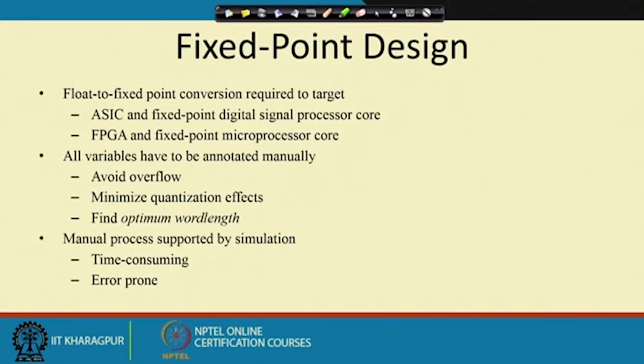Okay. So, if you just calculate the percentage of error, at that time it will be near about 17%. So, that means I am accumulating 17% error because of this floating point to fixed point conversion. Okay. So, whenever we are implementing the hardware, I have to find out what will be the optimum word length, so that this quantization error will be minimized. That is one thing.